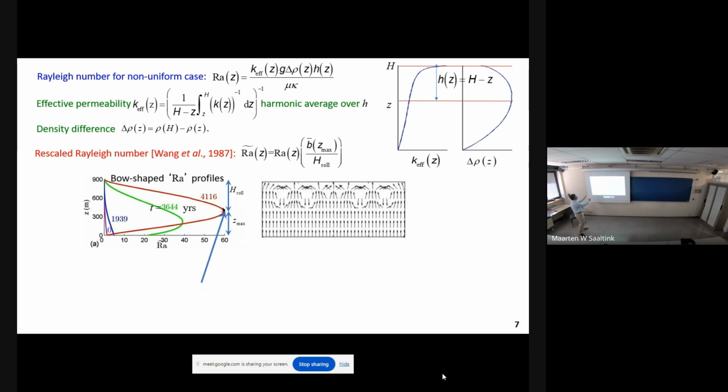So this is one set of analysis, and also numerically you can get the roll formation, that's the instability also. We found the height of the roll matching the height of the roll predicted by this calculation. Okay, and one more thing here. In a fracture where the fluid flows and there is Rayleigh-Bénard convection, there are two types of instability. One is called instantaneous, another is called delayed.